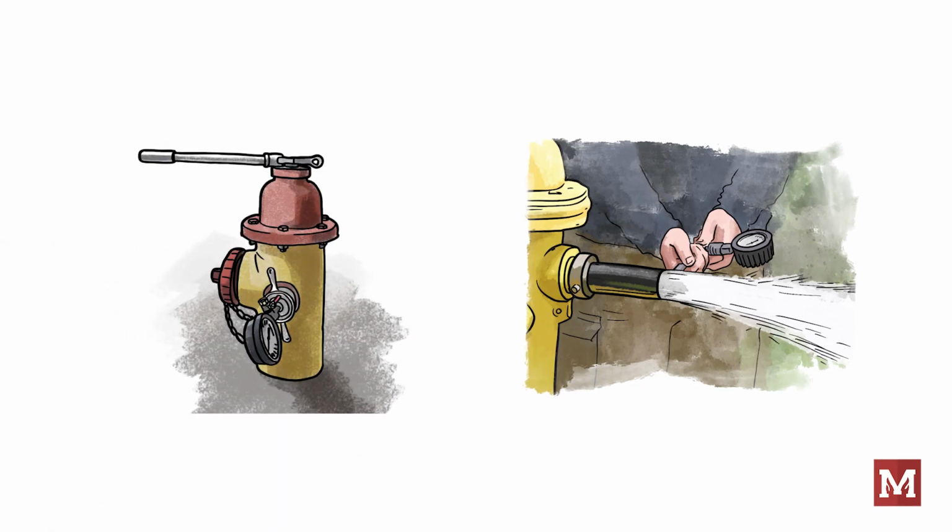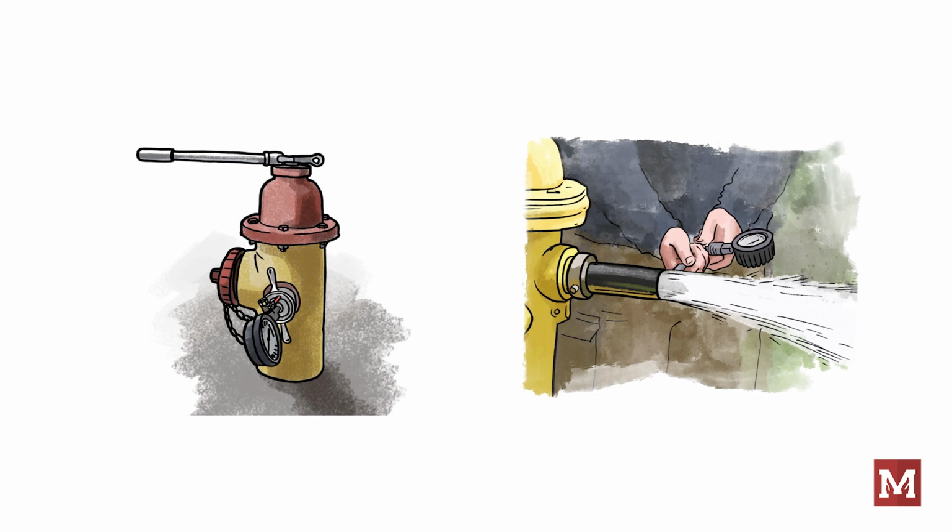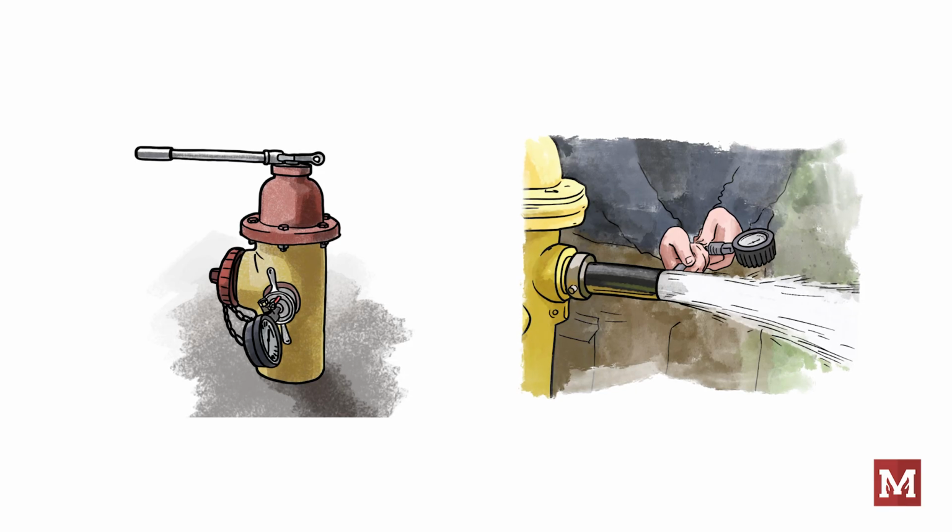Once we know what the water supply is, we need to understand where the water supply is. NFPA 13 requires our calculations go from the hydraulic remote area we discussed in the last segment, all the way back to the point where the water supply characteristics are known. In the case of a system being supplied by the public water supply, that point is the test hydrant.